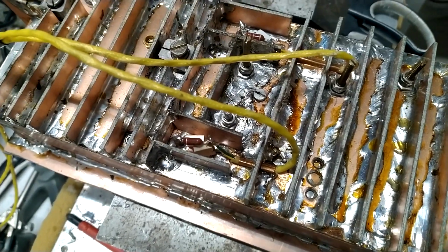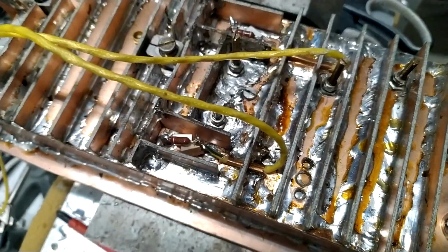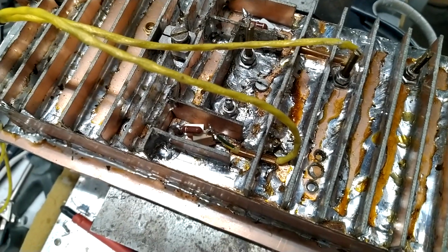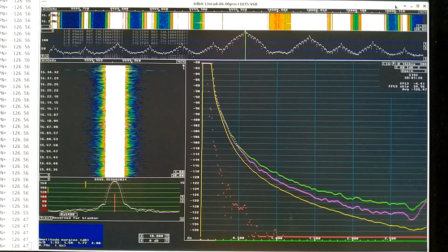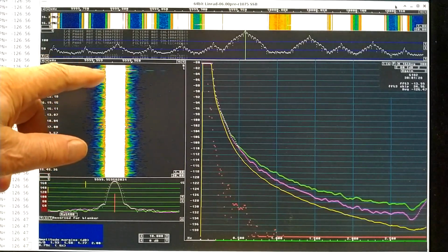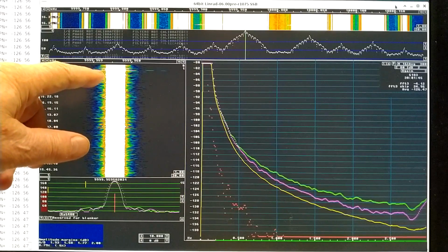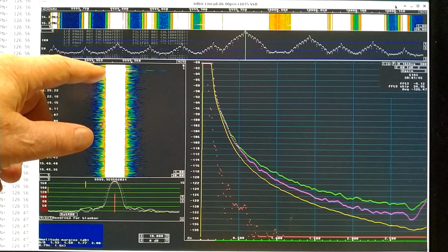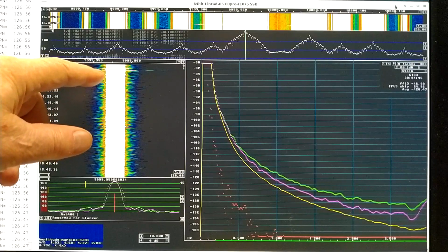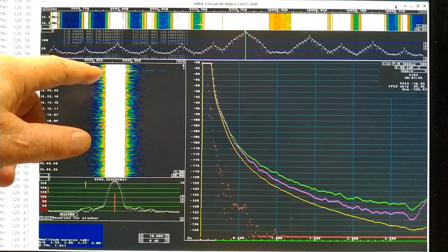This oscillator has now degraded. The phase noise is significantly higher than it was before, and I have done nothing, no change to it, it has just been running. The average noise, which was before minus 130, is now minus 126.56. It has degraded by 0.1 dB now, because when I started this recording I made some vibrations on the table while placing the camera on its, I don't know what it's called, the unit on which I have fastened it on the table.